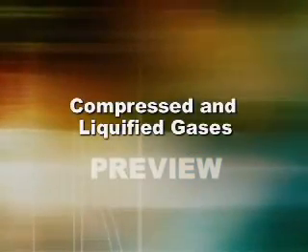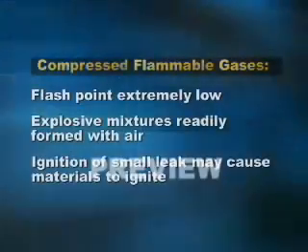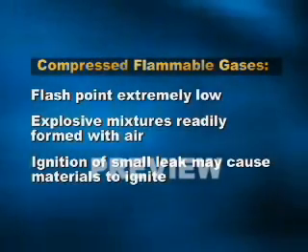Compressed and liquefied gases. The flash point of compressed flammable gases is extremely low and always below room temperature. Explosive mixtures are readily formed with air. Ignition of even a small leak may cause the materials to ignite.